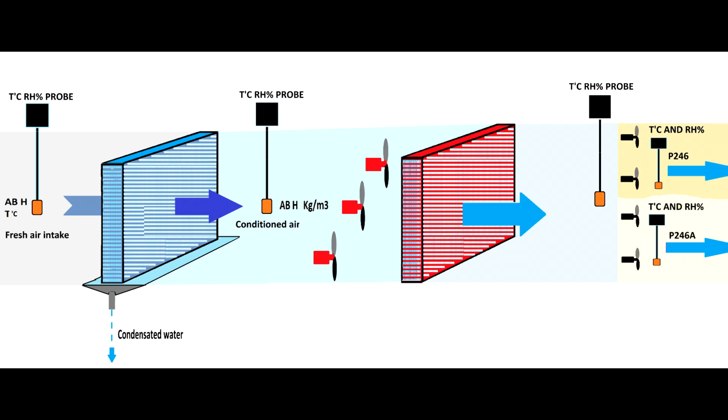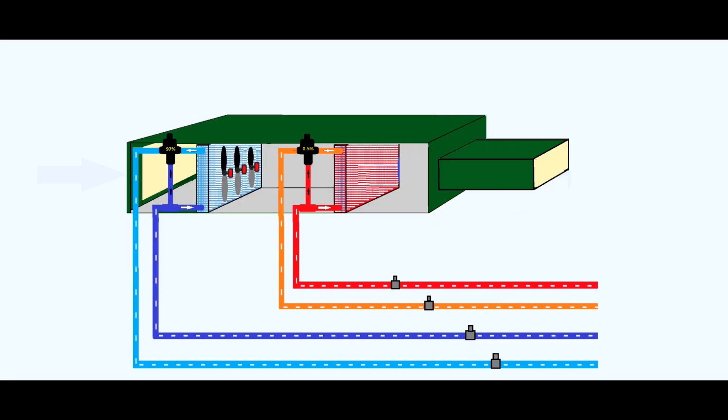Now this cooling heat exchanger has the capability not only to cool the air but to remove the moisture through condensation. That's why later on you'll find out that if you push more air than this heat exchanger can support, the moisture removing capability will be reduced. Now the heat exchanger is cooled by glycol which circulates through these pipes.